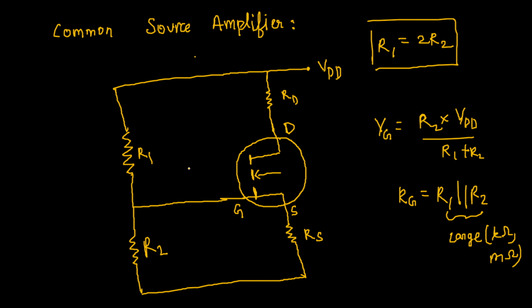With that said, the main difference that makes a MOSFET different from a BJT is that in the BJT we assumed IB to have some current, though it was almost zero for almost all calculation purposes. We considered it to be significant enough. However, in the MOSFET, the current that flows through the gate is completely zero.